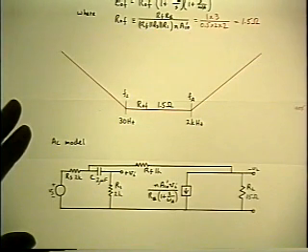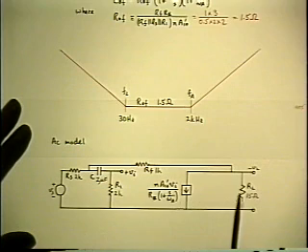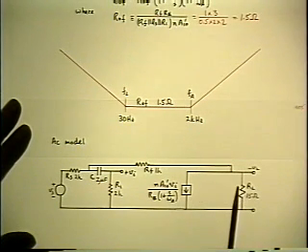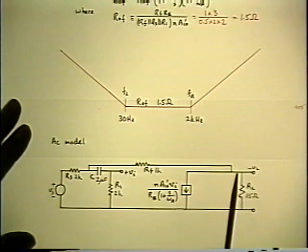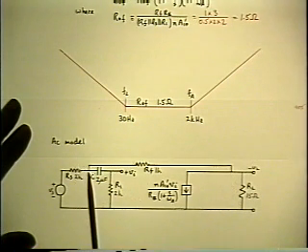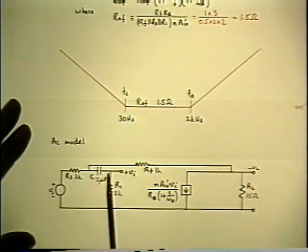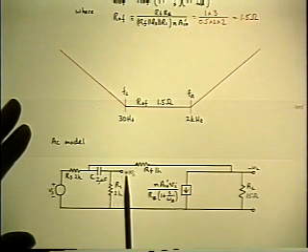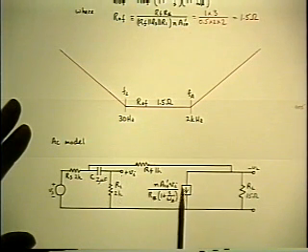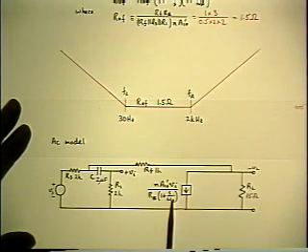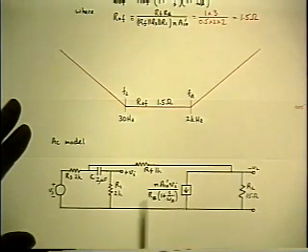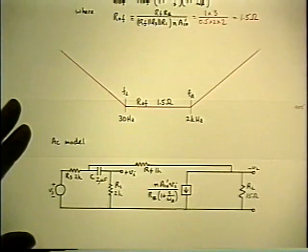Likewise, at infinite frequency, if you apply a test signal at the output, the signal would go down the feedback path and the coupling capacitor would now be a short, so you'd get a non-zero Vi which would activate this generator, except for the fact that at infinite frequency the pole would cause the generator to be zero again.